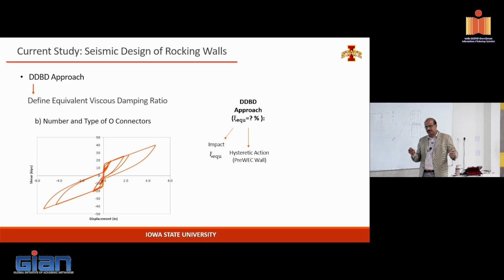And you don't shake too much, but one or two peak cycles will go through, but then the structure will have a permanent displacement. So we recommended what would be the ideal position so that you can rely on what they call a shakedown. After the peak excursion that took place, the structure goes back and forth because you still have the energy in the system. So they have to go through some free vibration back and forth.